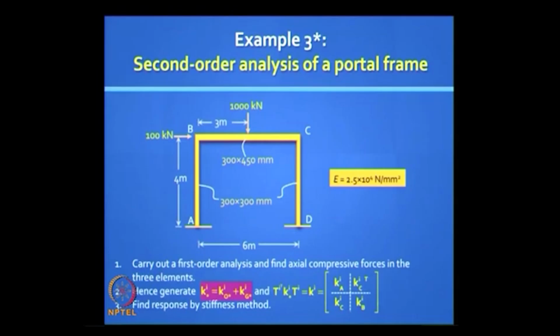Well, it is a reasonably correct solution, but if you want more accuracy, you should check out the actual forces you now get. Typically nonlinear analysis is like this: you do not know the actual forces, but you get a first order understanding when you do one run. Then you pick up the value, modify the stiffnesses with those values, and do a second run. You can do a third run; usually with 2 or 3 runs, and anyway the computer is doing it, you are not doing it. The effort needed is just to program it, you have a tolerance level and that gives you your complete solution.